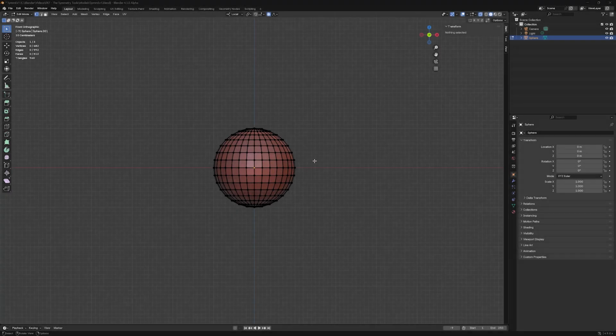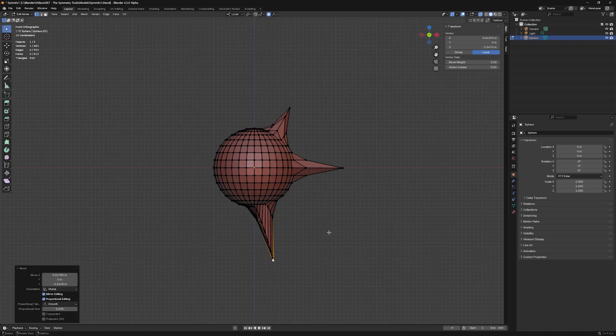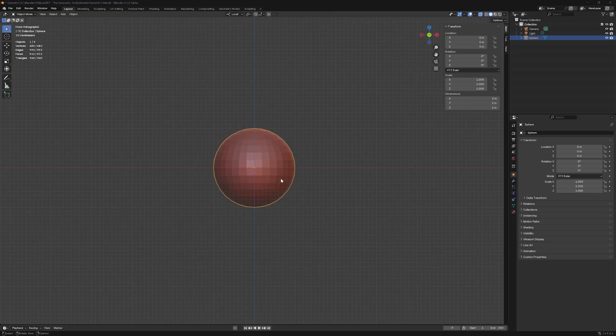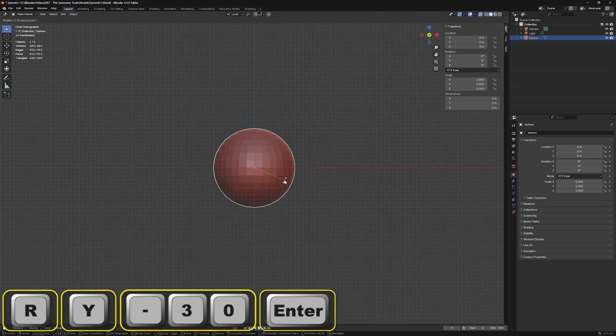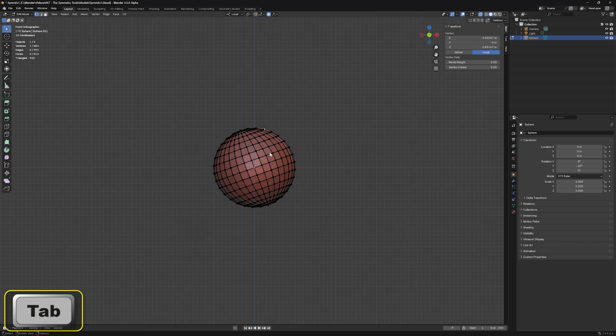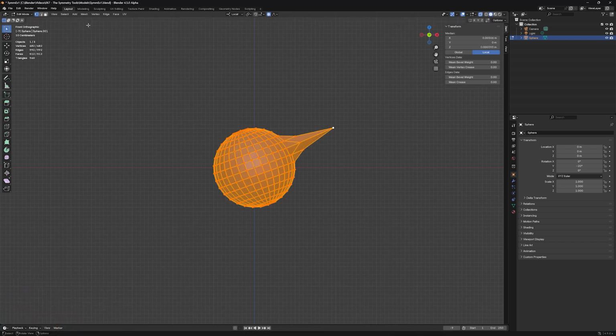In fact, the very first step in the example we just worked through isn't really necessary. We don't need to delete one half of the original mesh before we start modeling. The Symmetrize operation will automatically do that job for us. Another point to note is that the Symmetrize tool uses the local axes set when performing its calculations. This means that even if we've rotated our object before creating the other half of our model, the results are still correct.